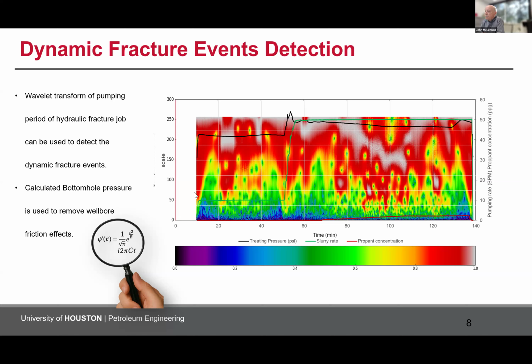No other questions, then I'll ask one. So Mohamed, have you been able to try this on data sets where things like plug bypass or screen out have occurred? Are there situations, as you implied, where a Nolte-Smith analysis isn't enough to diagnose an impending screen out?